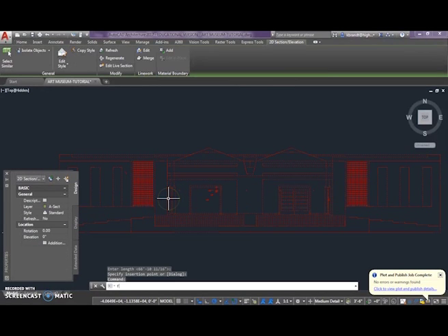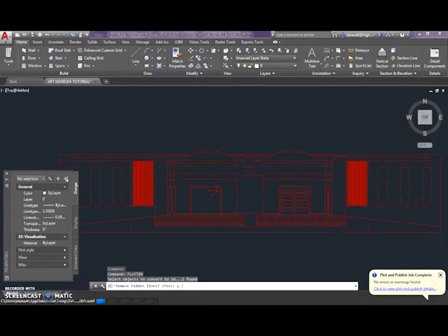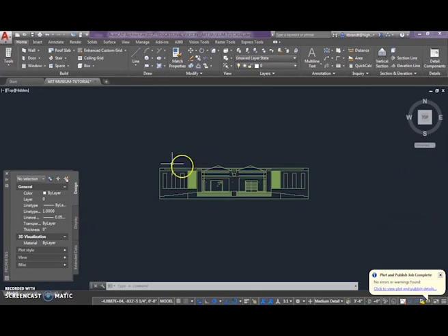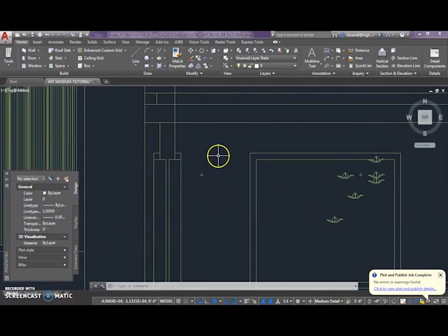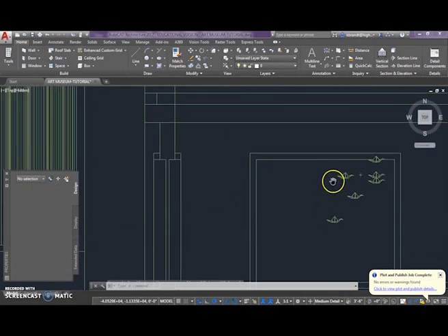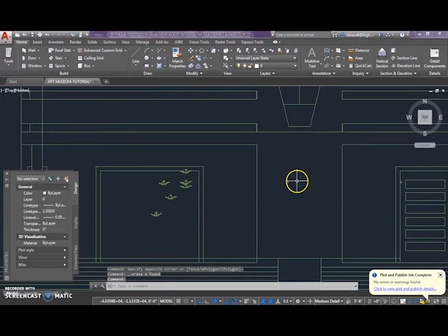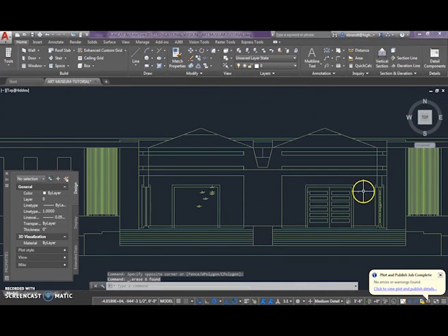Then you will drag your view box beyond the exterior walls of your space. Click and hit enter again. And then one more time click outside of your floor plan to insert the flat 2D drawing of your building section. So that inserts a block just like your hidden line projection does.